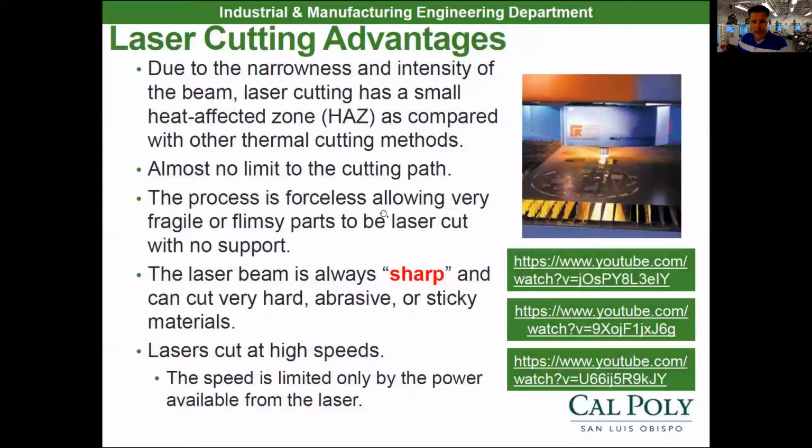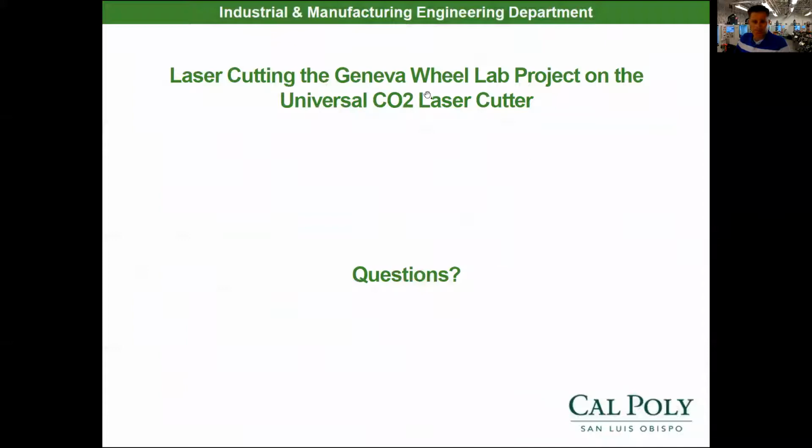So that's laser cutting. I don't have a video for you this week for laser cutting, because you're going to go in and do this in lab step by step, where you're going to learn how the raster and the vector functions are different in a laser cutter. You're going to use a DXF profile and learn how to cut these out. They come out in groups of 3. So you're going to get into groups of 3 in your lab, open up, program the laser, and make this part like you see right here.